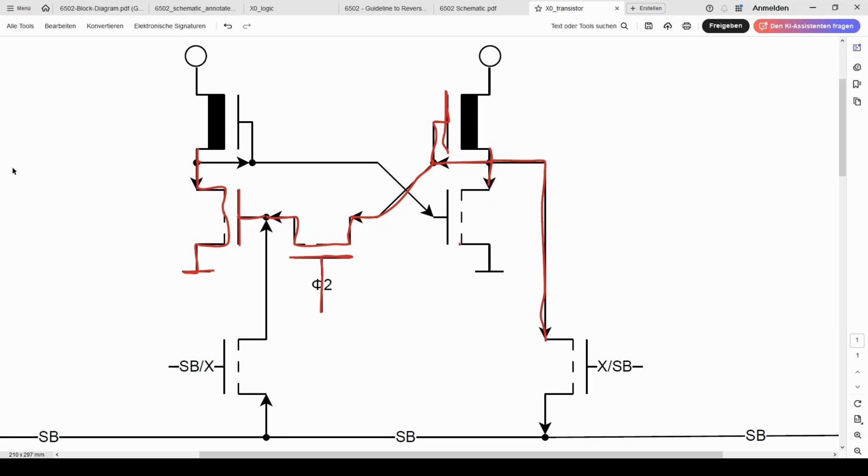And similarly, just like before, if we want to now reset this latch from the bus, well, once again, first the Phi2 transistor has to be off, so it has to block. So now power isn't going through here. Once again, at this point, if this weren't active, I guess the current would just linger for long enough that this doesn't just reset.